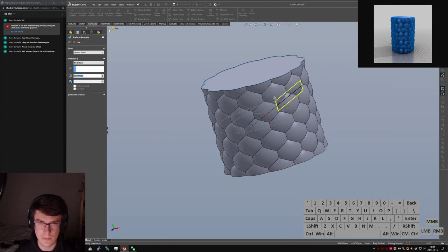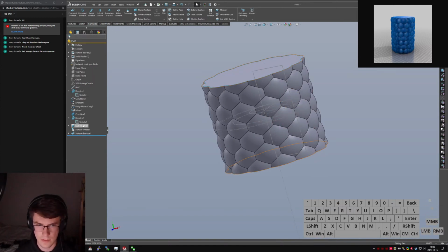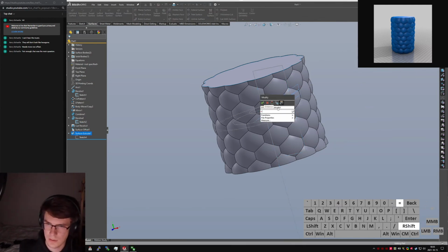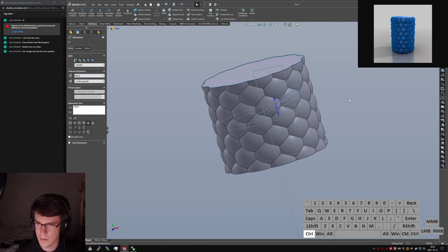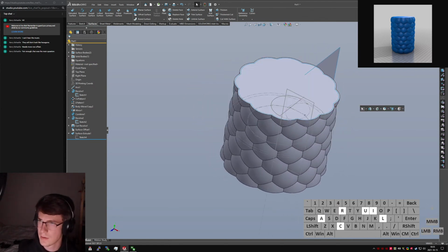Bidirectional. And then under, hang on, cut revolve. Or maybe it was under revolve 2? Yeah, it was under revolve 2. We'll leave that as 10 for now, and then take a quick look at this guy and say D1 at sketch 2 is how tall I want this to be. Rebuild. Perfect. Slicing plane. Circular pattern.